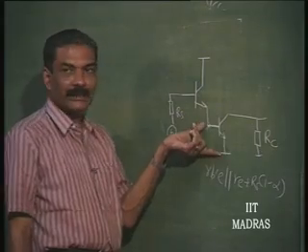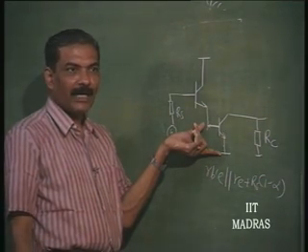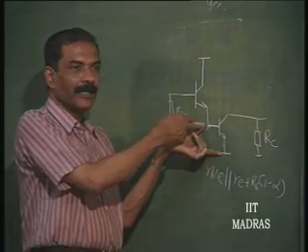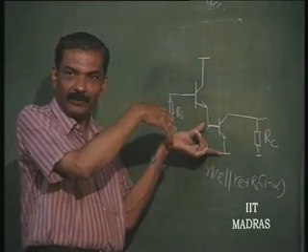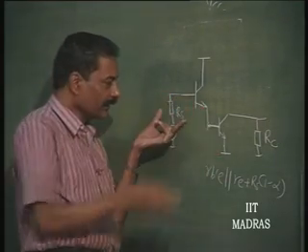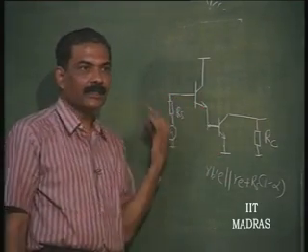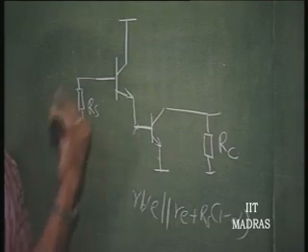So, the time constant here is decreased, that is, by artificially making it a better voltage source than before by using a common collector structure. Okay. So, in case RS is very large, this technique can be adopted in order to use this whole configuration